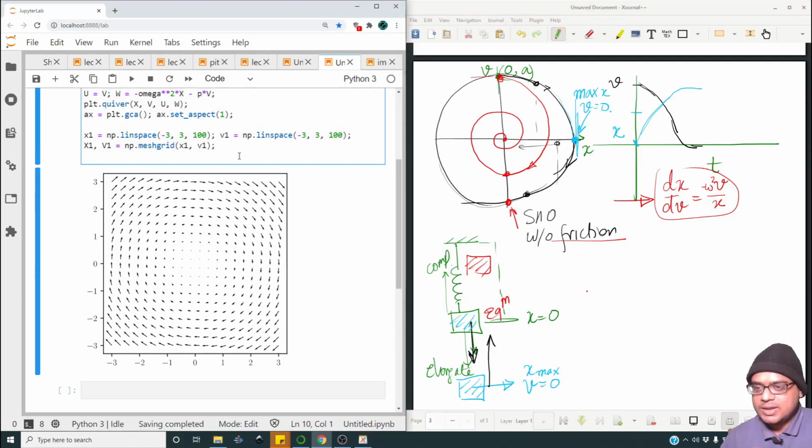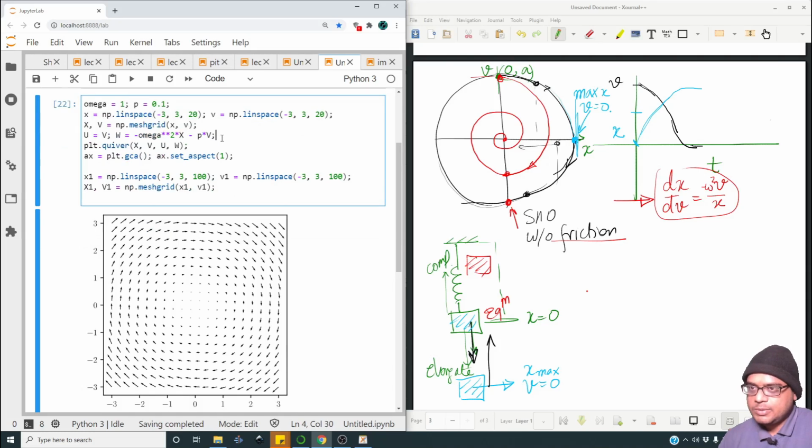And in NumPy, or even GNU plot, MATLAB, whatever, plotting a streamline is tantamount to using that velocity field and finding out the trajectory in that velocity field. Even if the velocity field is time dependent, you freeze the velocity field and find out the trajectory on that frozen velocity field. So now I've brought back x1 v1. Let me copy the expression with friction over here, and let me substitute this by v1. This will be x1 and this will be v1.